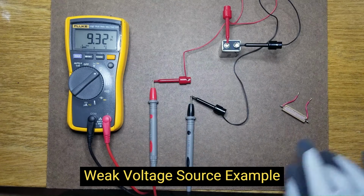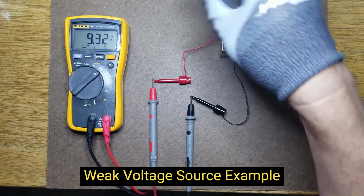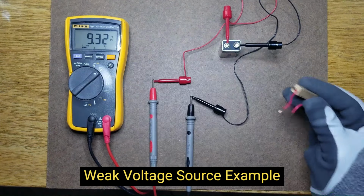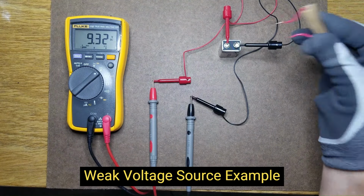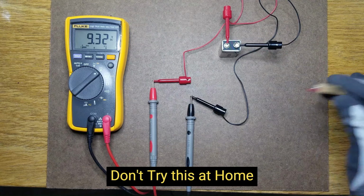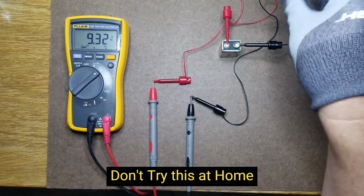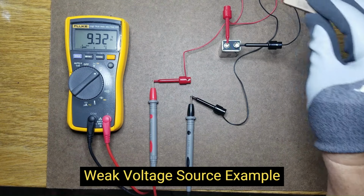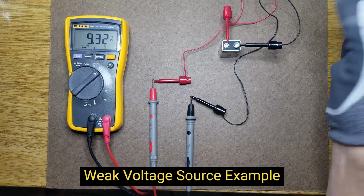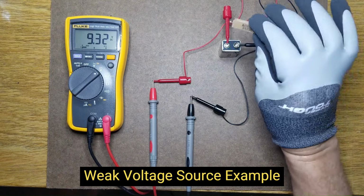It's measuring a little over 9 volts. And what I want to try to do is draw 1 amp of current off of this. Ideally, I'd want about a 9 ohm resistor, but I don't have one, so I've got a 10 ohm resistor. That's pretty close. I'm going to draw, using this, approximately an amp of current. And given that the 9 volt battery has about on average, 3 to 5 ohm output resistance, this should drop down maybe 5 volts, somewhere between 3 to 5 volts when I put this resistor across here.